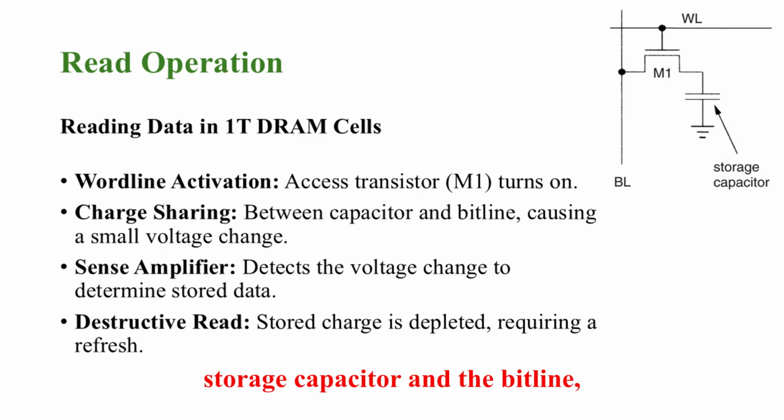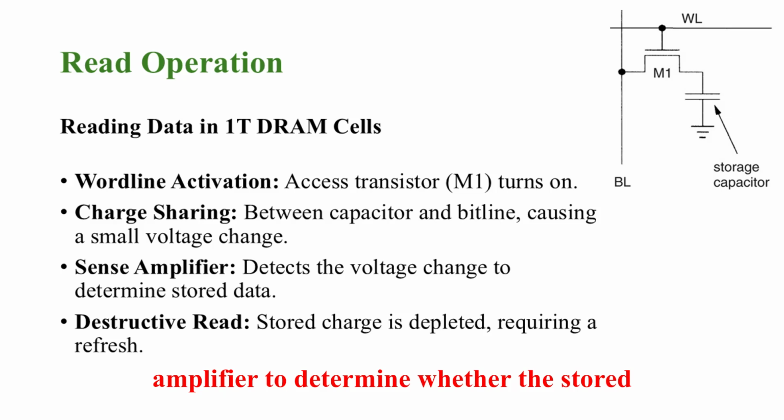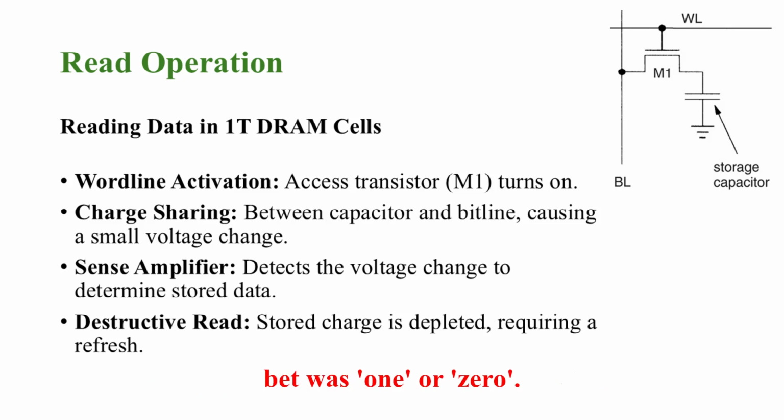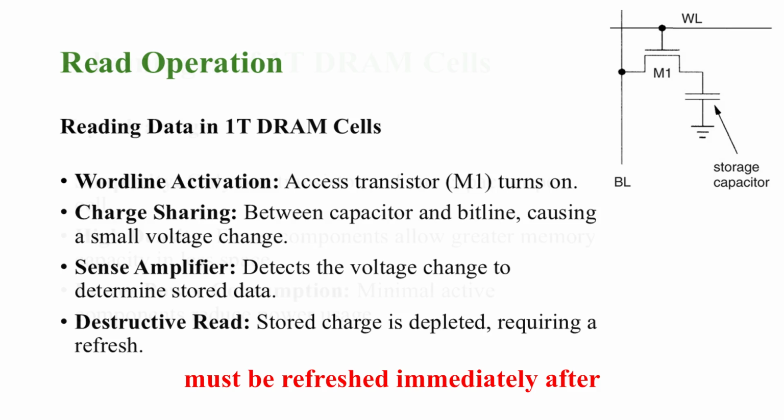Sharing charge between the storage capacitor and the bit line, causing a slight voltage change. Detecting the change with a sense amplifier to determine whether the stored bit was 1 or 0. However, this process is destructive, meaning the stored charge is lost and must be refreshed immediately after reading.